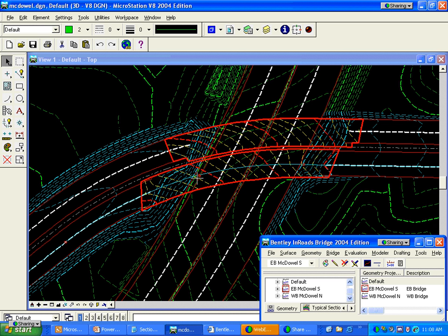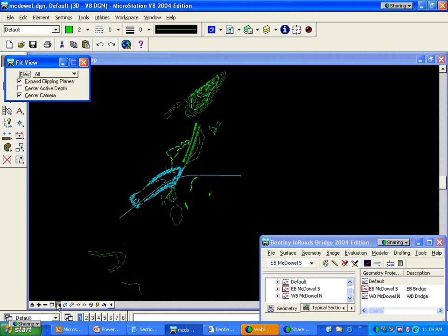And then we continue on at a radius here, and again we have another kink in the alignment to where it joins up to the tangent. So the tangent and the end of that curve are also not collinear. So that's kind of a complicated situation. I have a couple of profiles drawn over here to show you some of what's happening vertically.